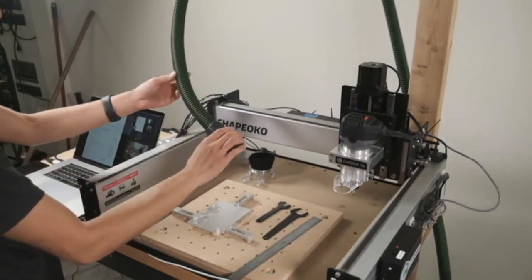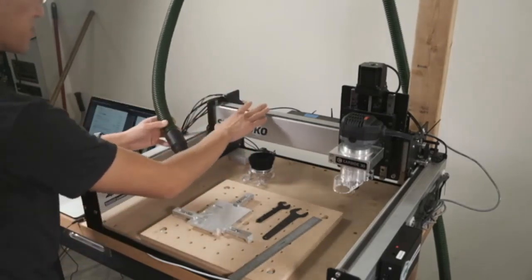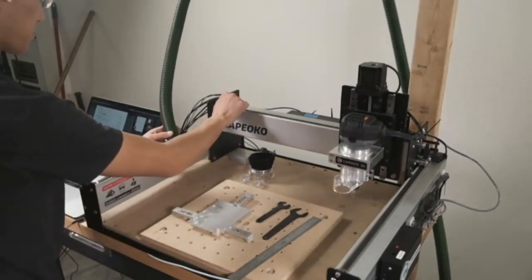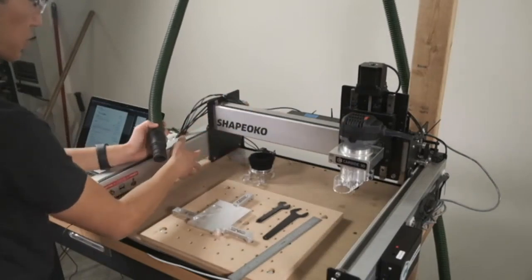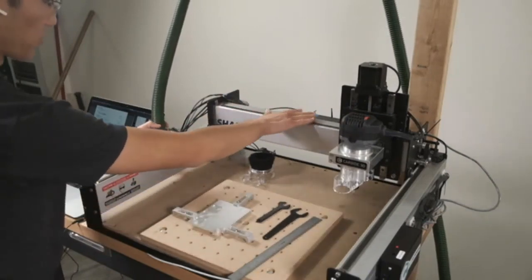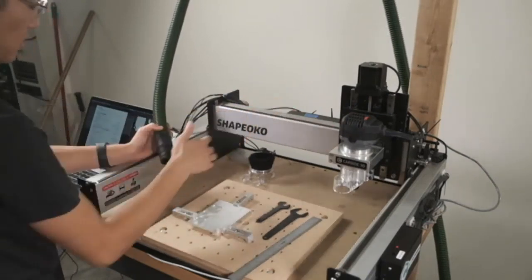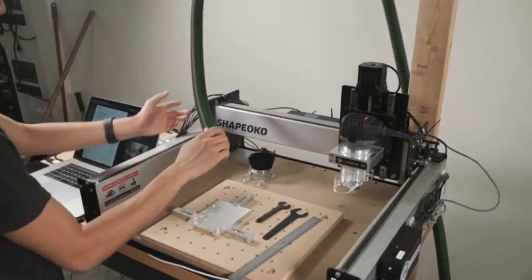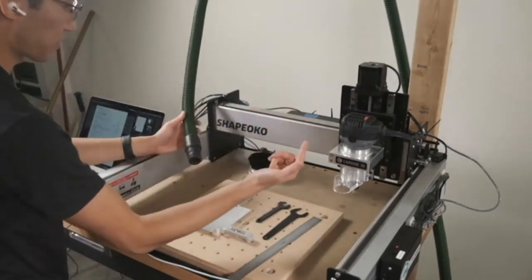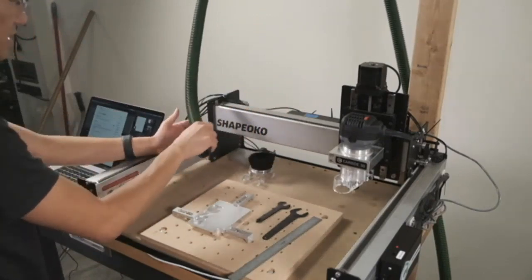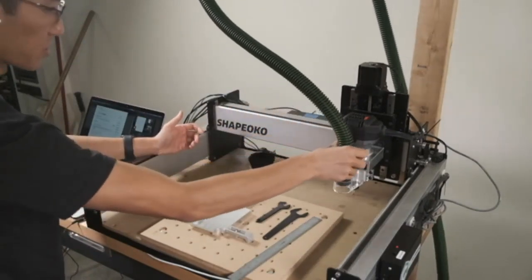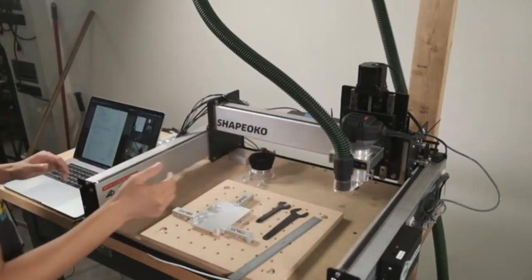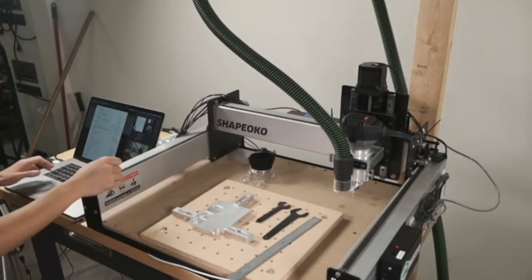And also physical isolation of the hose from the gantry, or whatever your electronics are mounted to, can also help. If you have just a hose that's dangling over this, it's transferring that charge into your machine. So being able to suspend the hose and keep it off the rest of your machine is also helpful.